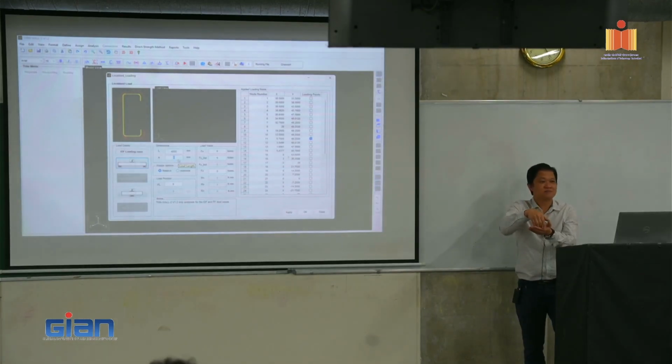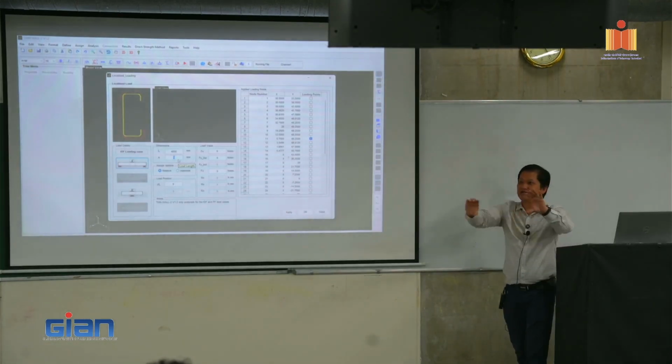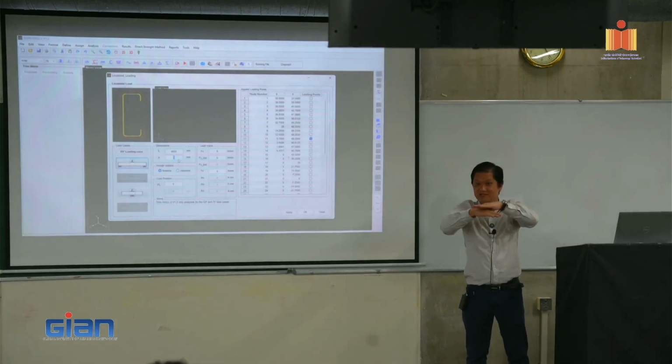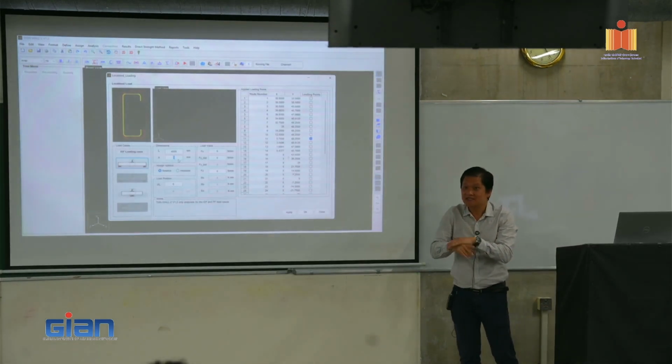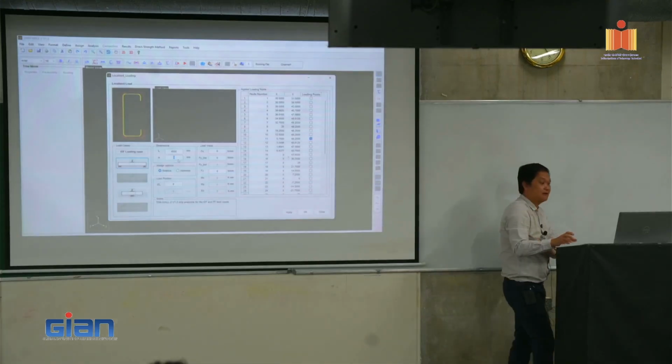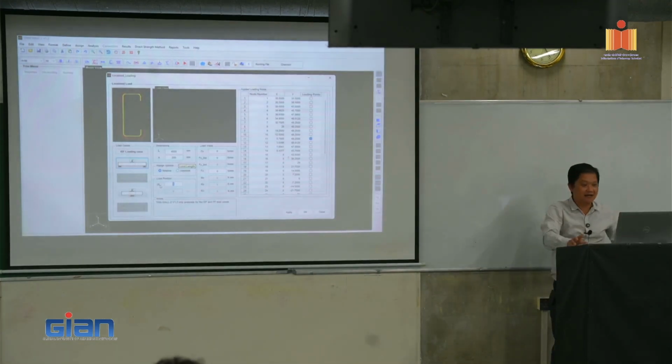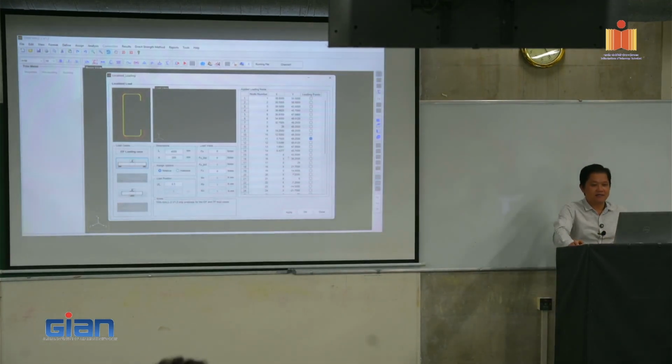So like, yeah. In practice, you have the purlin sitting on the top flange of a girder. So it's pushing down. Stiff bearing length. Yeah, this is the bearing length of the load. So like 200 maybe, yeah. And this is showing you where you're going to put it. I want to do it right in the center, the 0.5. And this is the load. So I want to put the load downward, so like 1,000, upward or something.